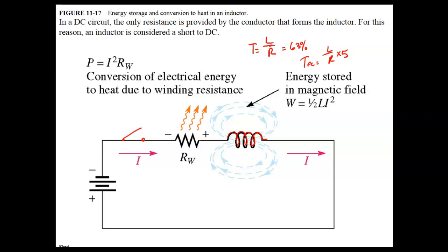The smaller the resistor, the faster the current comes into this thing, and this thing's going to oppose it. So this thing right here hates change. That means if I put this in an AC circuit, the higher the frequency, the more opposition this thing has. The lower the frequency, the less opposition it has.